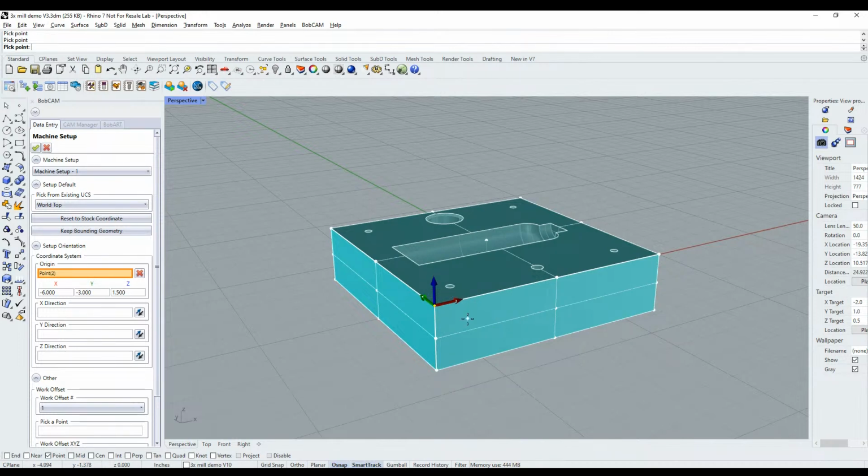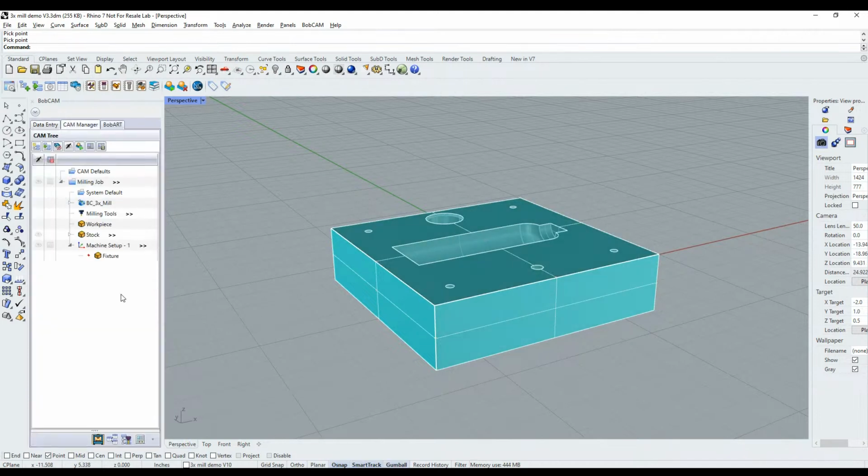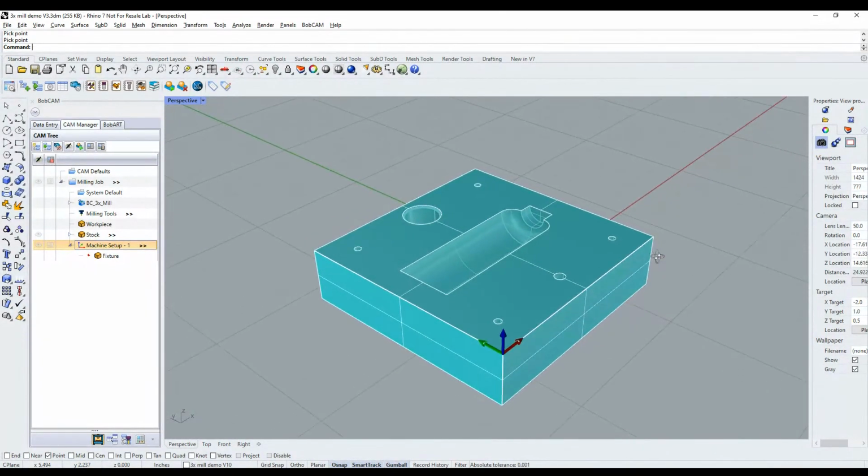And in the G code XYZ0 will be all referenced here at this location. If I'm touching the tool off at the center of the stock, for example, click on that point. Click anywhere there for my G54 location. So I'll click OK, and I can highlight machine setup at any time to see my G54 work offset location.